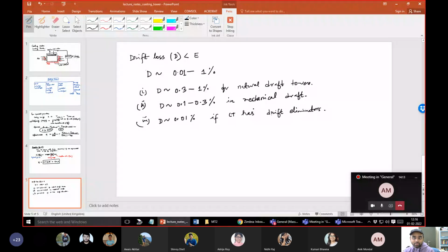And mostly if it's very hot, you can use that one instead of the glass, because the air will pass into it, whereas there is shade due to these loops, right? So these loops you can think of as a kind of drift eliminator. There is a sudden change in the direction on the impact of the air on those drift eliminators, and generally they are also circular in type.